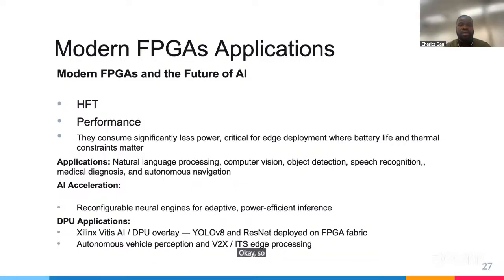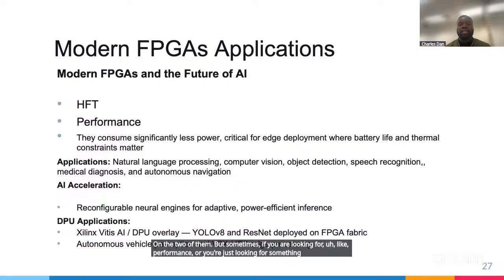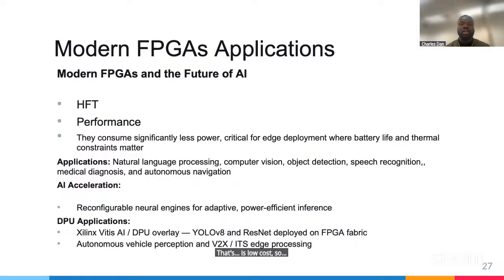Okay, so there are quite some projects that can be implemented on both of them. But sometimes if you are looking for performance, or you are just looking for something low cost, you wouldn't want to spend so much on an FPGA, because it depends on what you want to achieve at the end. A microcontroller is just like an ASIC, in the sense that once it is taped out, you cannot change the hardware configuration.